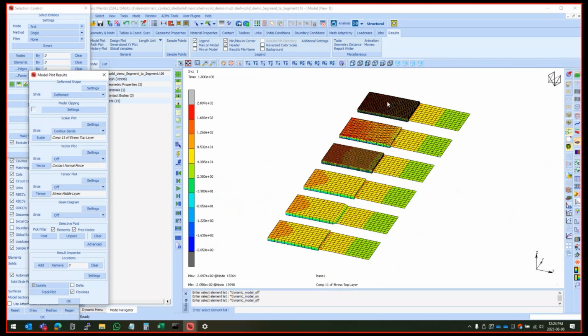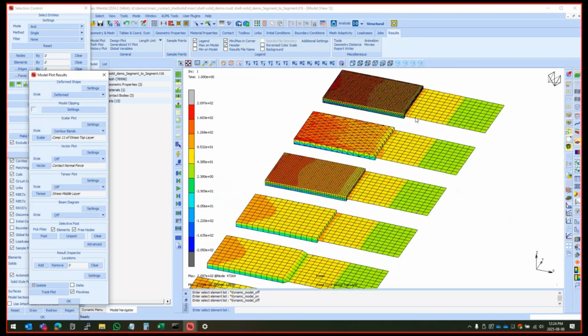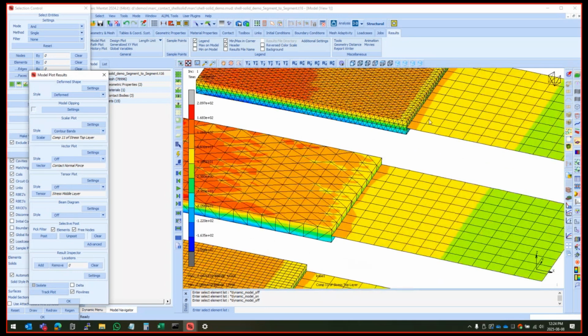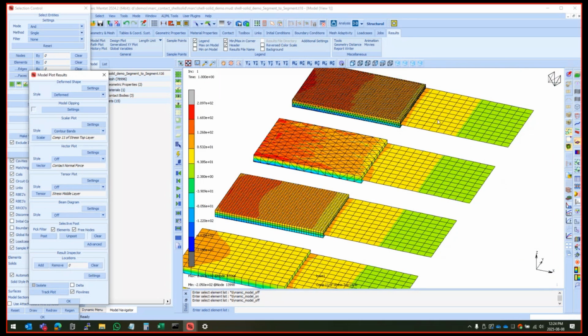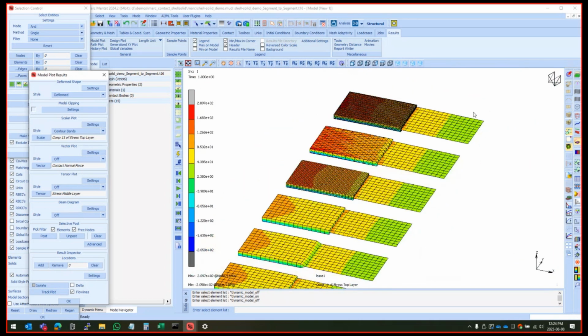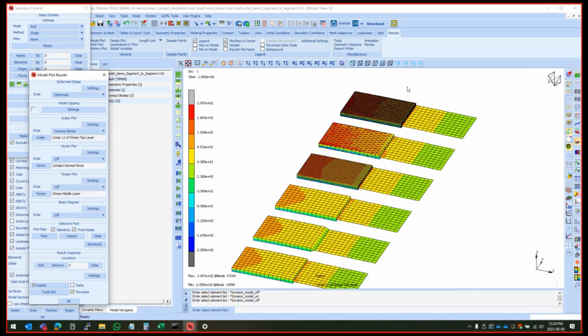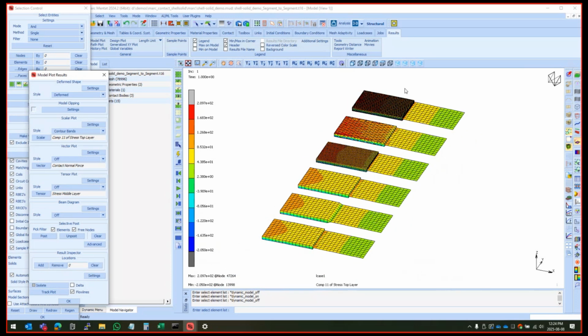I mean, that's the purpose here was more to show how to get correct load transfer from shells on this side to solids on that side. Meshing finer, either like this or meshing with only solids, only shells, will show you what the actual stress is. Okay, just to compare these stress distributions with the actual case, that was my point on that. If it's easy to add.